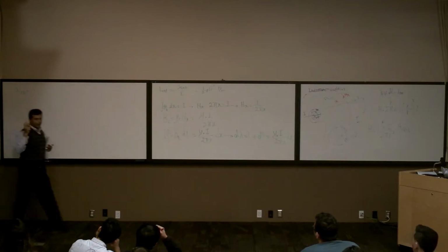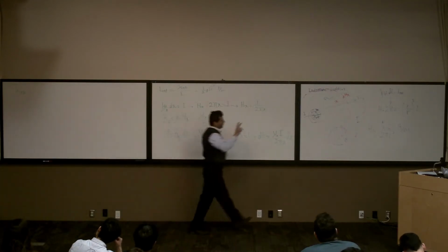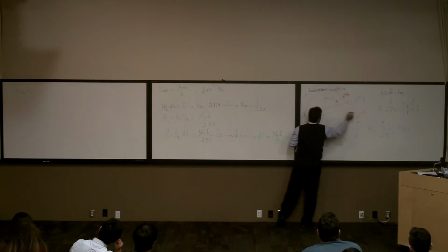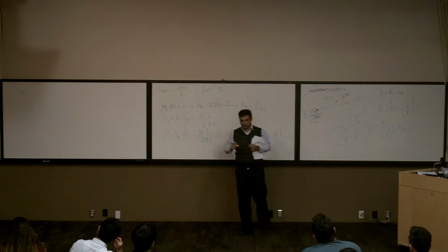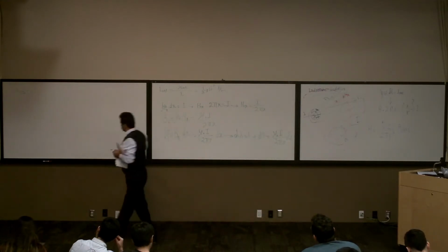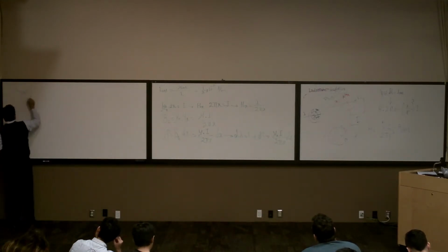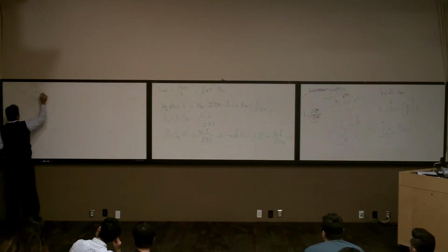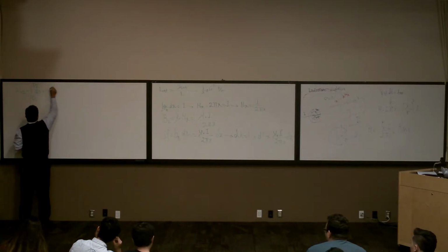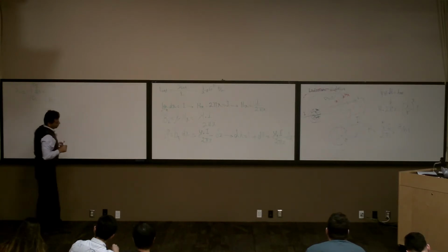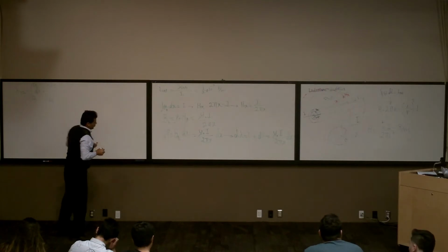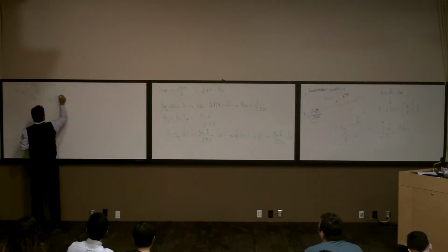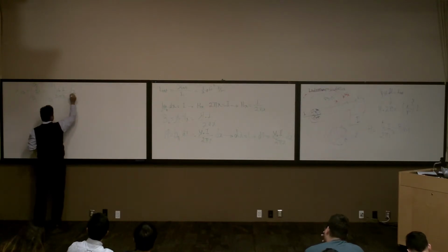Lambda 1, 2 means how much flux linkage we have in this area. I want to see how much flux linkage I have in this area. So what should I do? I should take an integral of d lambda from d1 to d2, right? So basically, it's going to be the integral from d1 to d2 of mu0 I over 2 pi x dx.